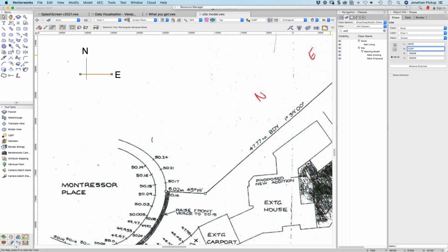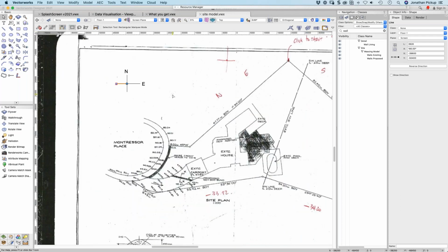It's completely, I don't know how to put it politely, back to front. You know what I meant, Barry. Okay, the surveyor calls that one 180 degrees. Vectorworks calls it minus 90. And the surveyor calls this one 270 degrees, and Vectorworks calls it 180. It doesn't relate to what we're looking at, does it, Jane?